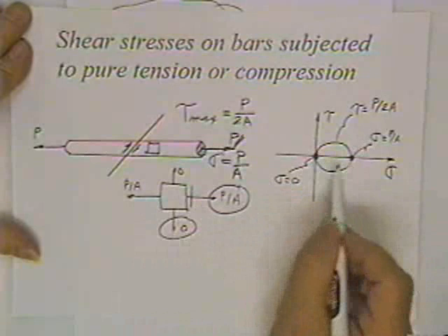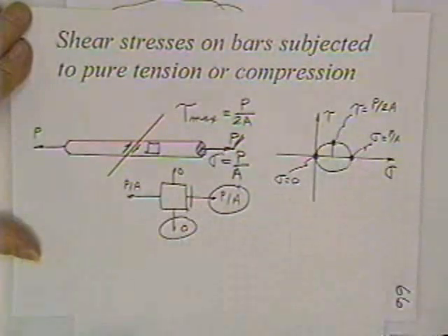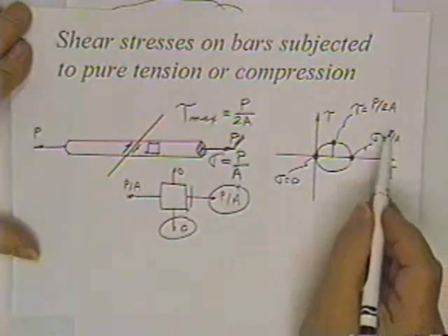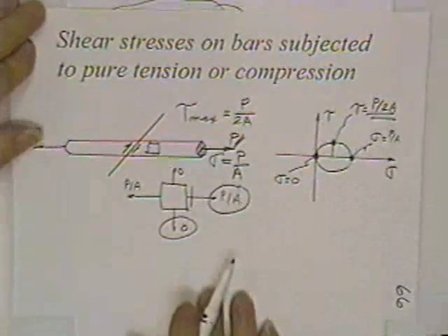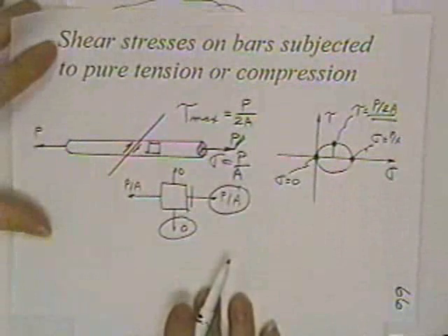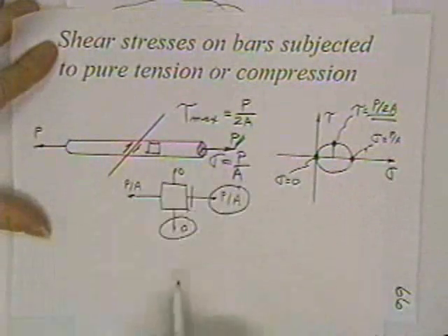There's no P over A and no shear. You draw a Mohr circle, look at that. That tau has a value. It's actually half of the P over A stress. So be careful. The trick for all profs, perhaps the exam, will say, how much shear is in a bar? When the guy didn't shear it, he just put pure tension. There is some.